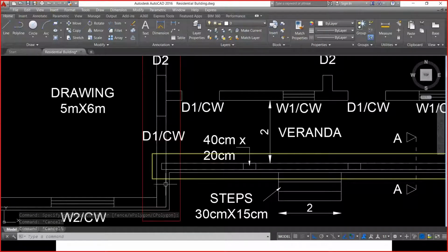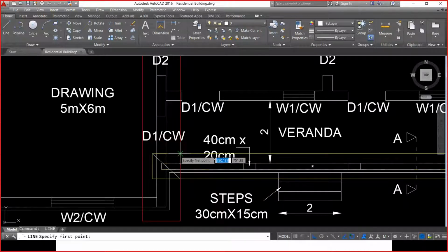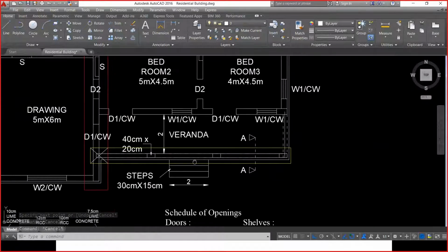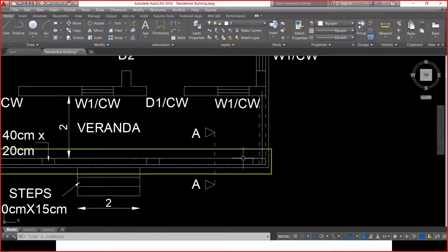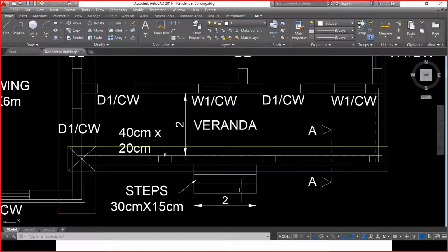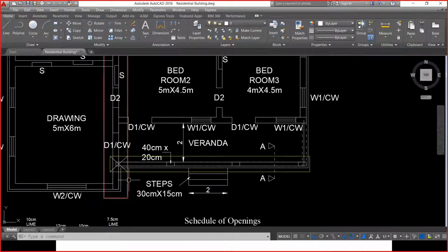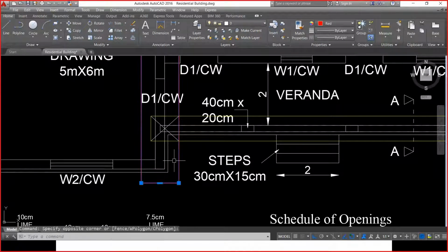Right? I need to avoid this area, which I'm going to cross mark. This area I have to deduct because it is already done, right? Similarly, when I come to this and there is no excavation done, this is the first time I'm doing excavation here, then no problem. But only here I have to do the deduction. But that too, the deduction cannot happen for the same width which is already done.